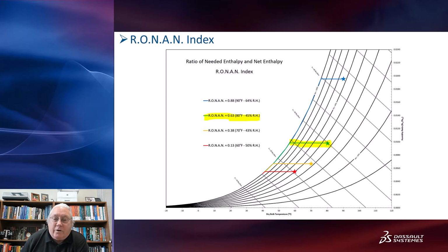Once you get to this curve here, you continue to input energy, and your temperature can actually start going down, because the energy going in here is going into reducing the temperature, but you're not creating any water. Once you get to the 100% curve, you go down this curve here, and then you're generating water all the way down this curve. And my target temperature was 40 degrees Fahrenheit. You don't want to get it down to freezing, otherwise you'll freeze up your condensation plates, and that's no good.